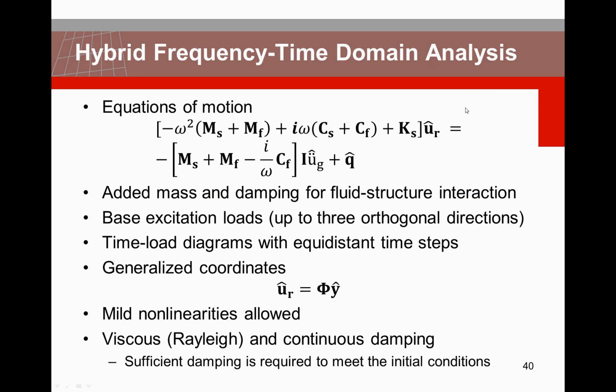A special type of analysis is the hybrid frequency time domain analysis. What you see here in the equation of motion is that, in the case of fluid structure interaction, because this model is built for fluid structure interaction, for analysis of dams, we can have both the added mass and the added damping of the fluid.